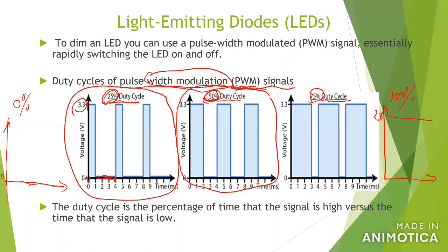If you want a high speed motor, you output a 100% duty cycle PWM signal. If you want a slow motor rotation, you output something like a 25% duty cycle PWM signal. So by adjusting the PWM duty cycle values, you can change the motor speed and dim the LED lights. That's the way you control these kinds of devices.